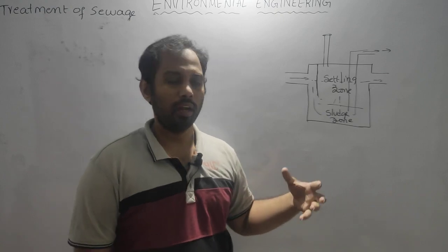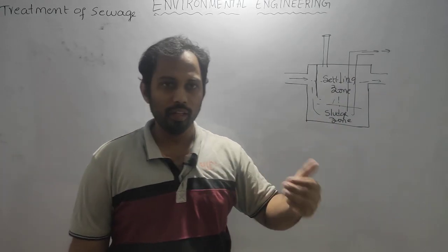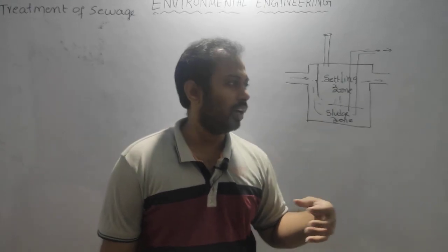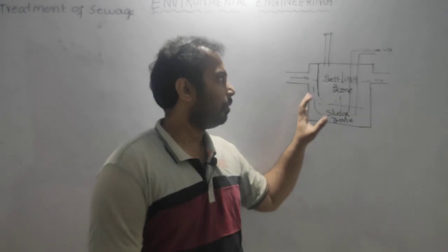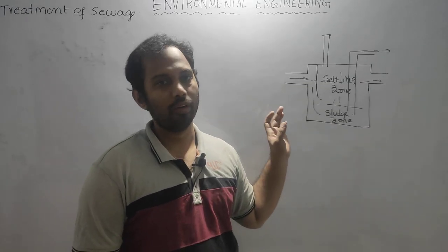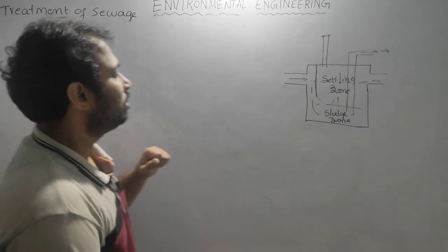So those kinds of mechanisms: the effluent will not go directly into the drains, it will be land irrigated using soak pits and dispersion trenches. So likewise we work. That is the complete process flow of the septic tank.